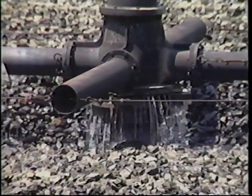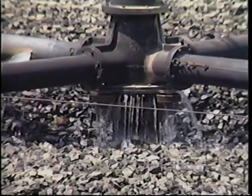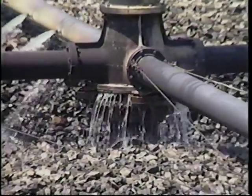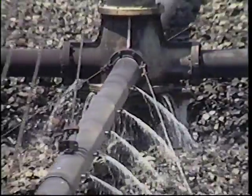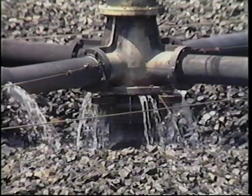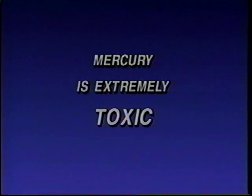In the center column of the rotating distributor, you will find bearings and seals that must be maintained. If the seal in the center column is leaking excessively, it should be replaced. Leaking seals can lead to poor trickling filter performance. Warning: some older trickling filters may be equipped with mercury seals. Mercury is an extremely toxic element that requires special handling. If your trickling filter is equipped with a mercury seal, notify your local DEP office at once.